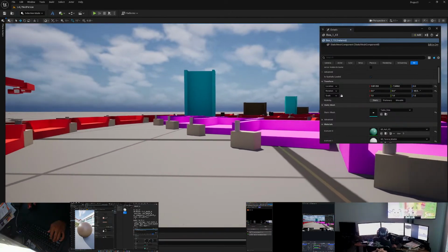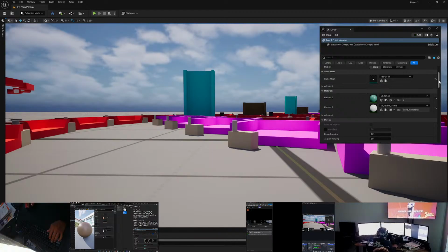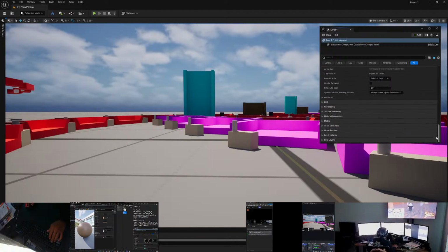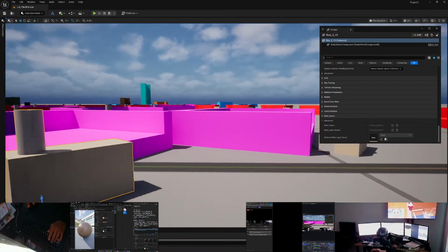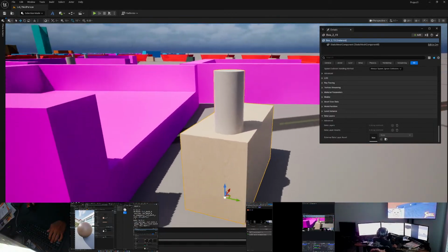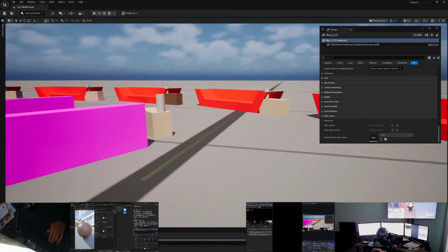And if I have a problem with saving, typically what I would want to do, and I think this might be in the details panel, see data layers. For each object, it's possible sometimes you'll have a data layer that's connected to Datasmith. When you can't save your project, you need to delete the Datasmith data layer out of the mesh.